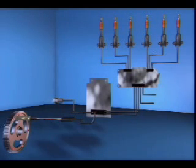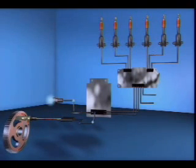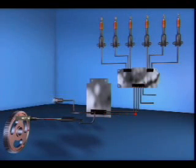This diagram shows the major components of the ignition system. The input devices are the engine position sensor and intake manifold absolute pressure sensor. The ECM is a processor and an input device to the ignition control module, or ICM, which is also a processor. The ICM outputs a signal to the coil-on plugs mounted on each of the spark plugs.